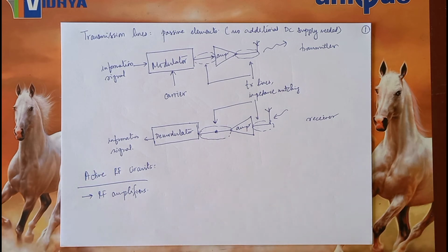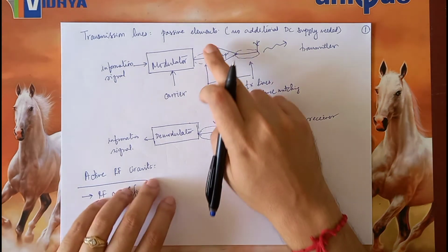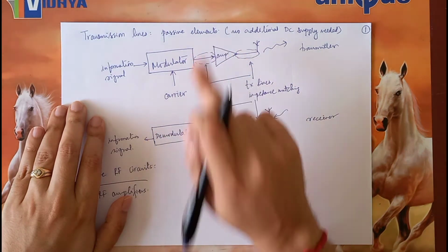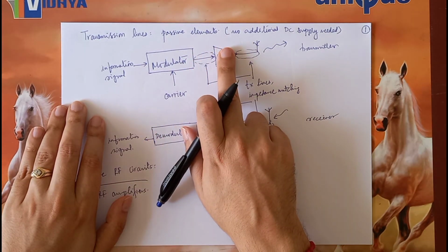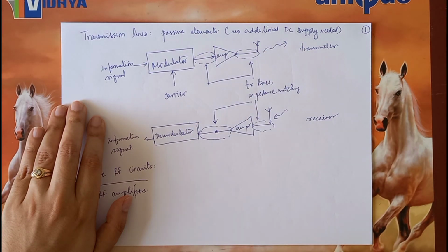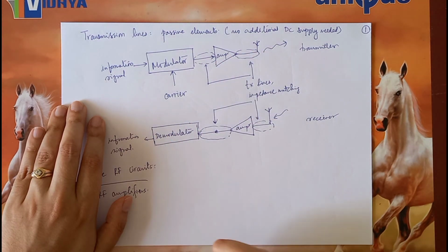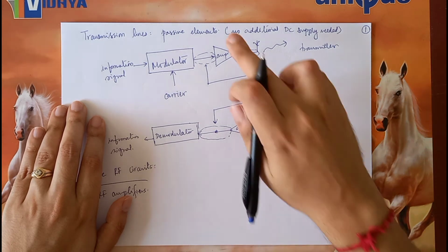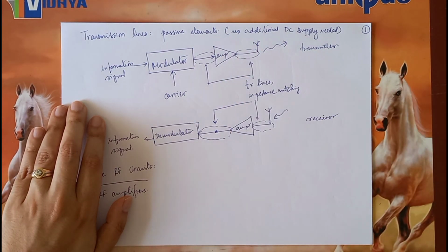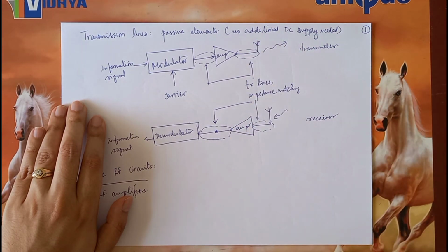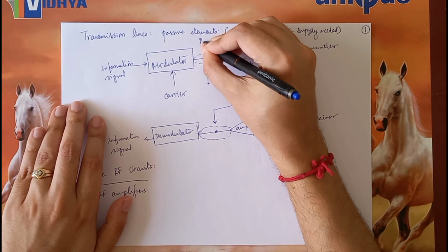It does not have a very clear idea of where the nearest base station is. So what it essentially has to do is to take this final signal, this modulated signal, and provide the maximum possible gain over here, so that the antenna can pump out the maximum possible power. This kind of an amplifier, where the concern is on the highest possible amount of power that can be transmitted, these kind of amplifiers are called as power amplifiers.